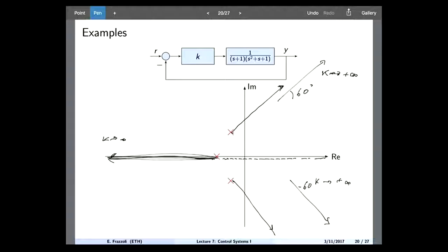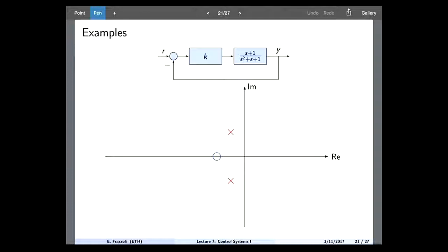It becomes unstable, okay? And this is what happened when people started designing, for example, controllers for helicopters. Helicopters happen to be a third order system. If you crank up your gain too much, then you think that you're making the system more stable. No, no, no, you're actually making it unstable. Okay? And again, this is another example where you see that just by sketching this 5-second root locus, you can understand some of these properties. In this particular case, using too large of a gain will actually give you instability. Okay? Okay, fine. We'll do more examples in exercises and next time.